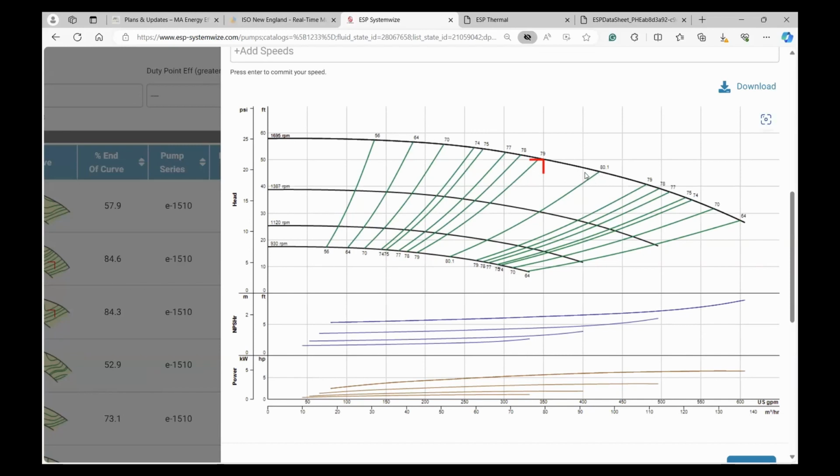Also factoring in, if you have, let's say, a sensorless control, or if you even have sensored, but the sensors are on the unit, just consider some of these curves that are quite flat, where maybe the difference between even 2 PSI could be the difference of several hundred gallons a minute. Just be a bit hesitant. So as you start looking at any of the sensorless units, they're all basing it off of motor current.